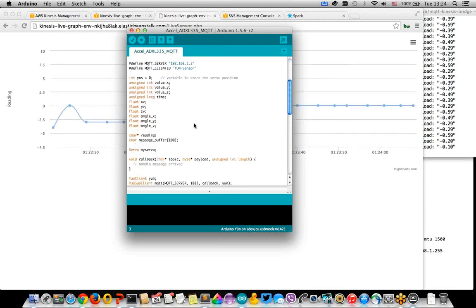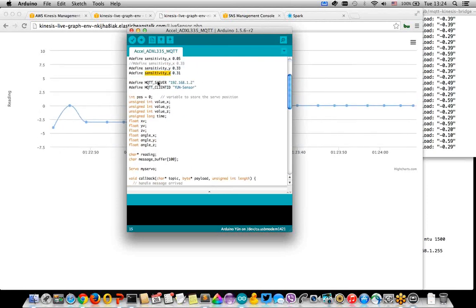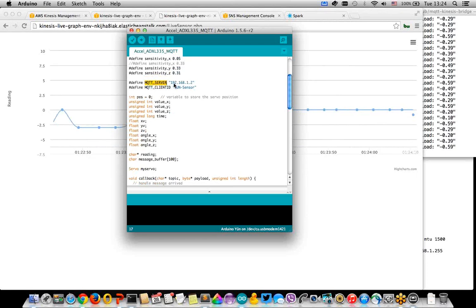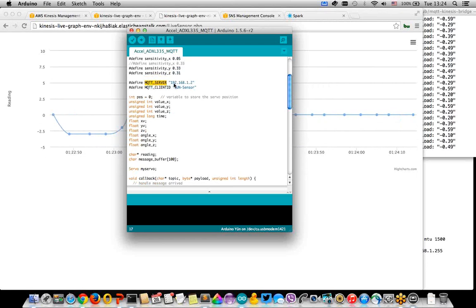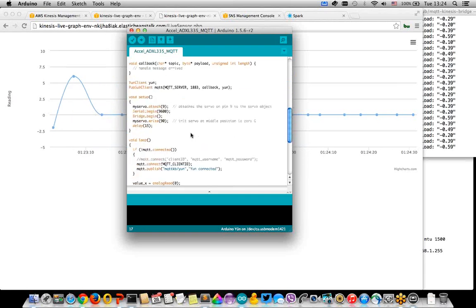And the code is really quite simple. I'm going to show you the major parts here. My MQTT server, the Raspberry Pi, is this. I happen to use static IPs. A better way would be to have dynamic addressing and dynamic service discovery, which would be more complex but more future-proof. So in this case, I have hard-coded the address for the Raspberry Pi for the Arduino.